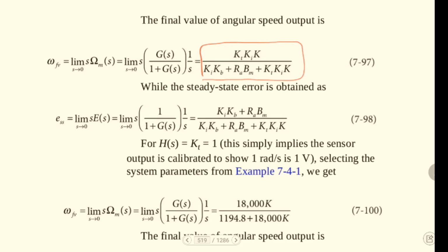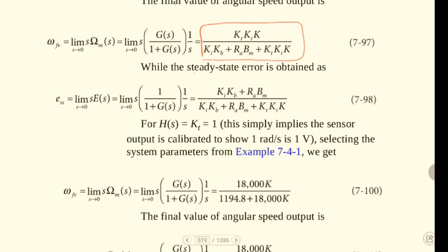So, how can we find the steady state error? We can use the same relation here. When you put the parameters in here, kt is 1 as you see for the unity feedback, we can easily get the steady state error like that. What does it mean for the steady state error with respect to the k value or controller gain? As you see here, this is the denominator value again. If the k value is increased, ESS can be decreased.